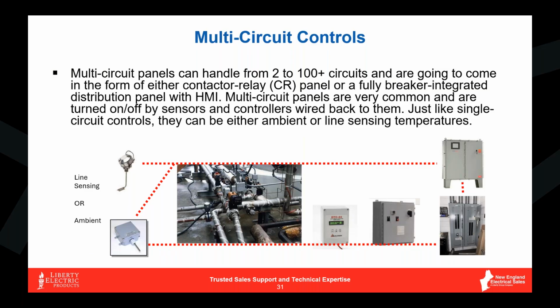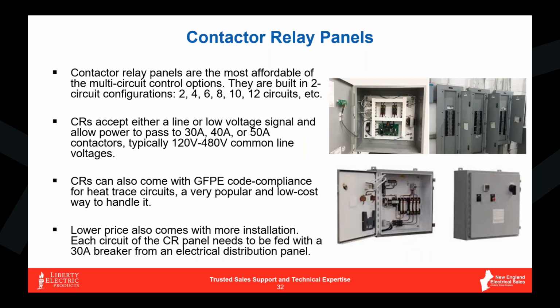And when it pings and it has a positive connection established, it'll allow those contactors to close and send power through the unit to your heating cables. The big panel sitting above that entrance panel in our graphics on the bottom of the screen, those are fully integrated breaker loaded manufactured panels by Chromalox, where again, you would not have to bring breakers over. You just bring like a single 100 amp or 200 amp feed into the unit itself, and then it distributes the power. So we'll touch on that in just a second.